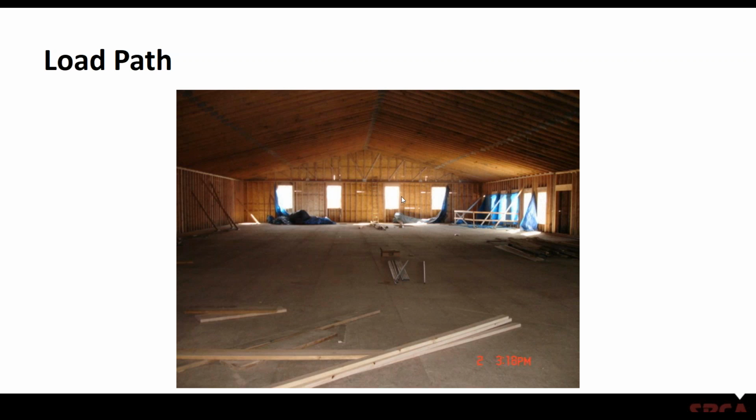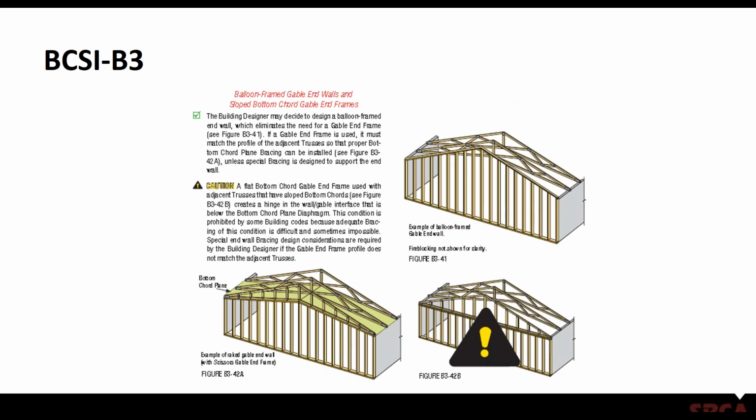They ended up providing a structural gable truss with a flat bottom at the end of this sanctuary to make it easy for the framer to frame that wall. But what you have is a hinge point where that bottom chord ties into the top of the wall. I went over to this wall, and just by applying some lateral pressure, you could shake it. It definitely moved.